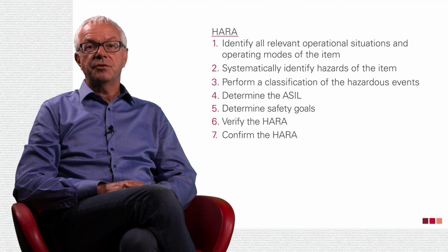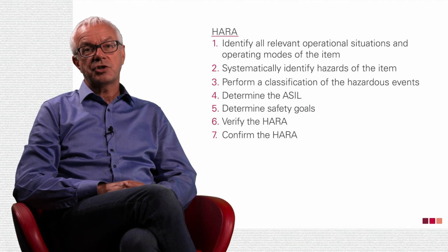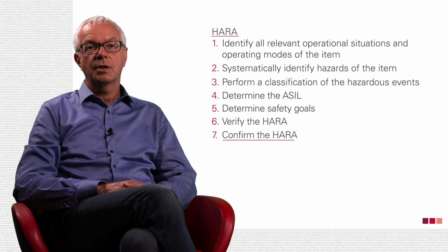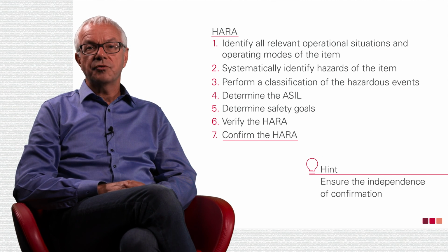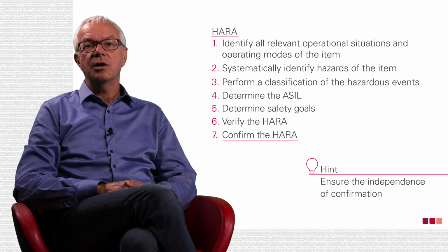The seventh and final step is to have each HARA assessed by a person outside development. You need independent confirmation to be sure you've established the correct ASIL and the ISO 26262 criteria for a HARA have been met.